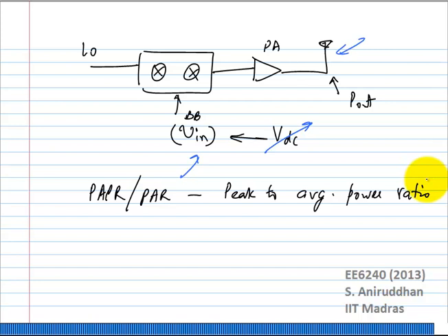And that is what you mean when you say it's a linear amplifier. The amount of clipping you see on the peak signal, you might get some clipping, but that amount of clipping is acceptable because it might degrade the error vector magnitude, EVM, of the transmitted signal only by a very small amount. Now the more you clip it, the worse it gets. As simple as that. Okay?